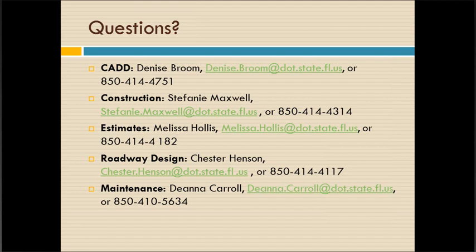If the thermo is included as part of the construction contract, does the current 710-90 final surface note apply, or does it need to change? There will be an updated specification that takes care of that. You won't need to say how many layers there, because the updated specification will say if there is thermoplastic in your contract, then you only need to have the 1 layer.